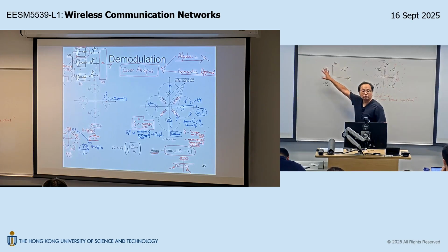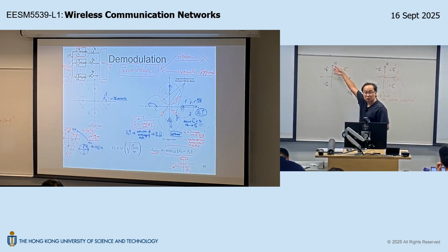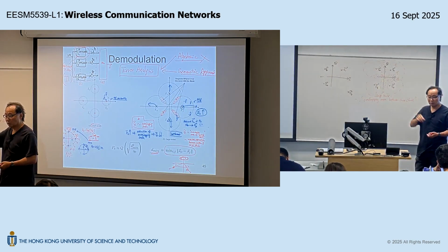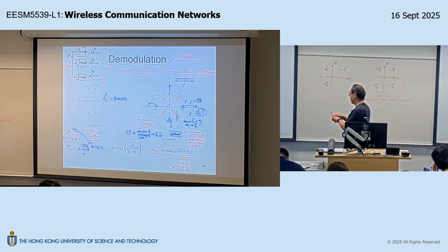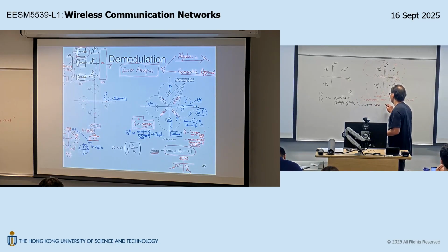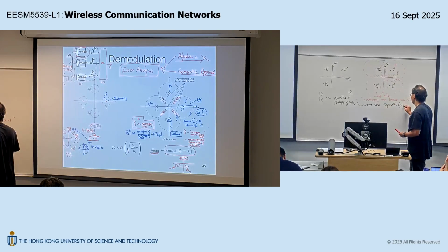So when you have more than 2 points, more than binary modulation, then the error probability is determined by the bottleneck, the worst case overlapping areas. Put it this way: the worst case overlapping area depends on the worst case separation of constellation points.